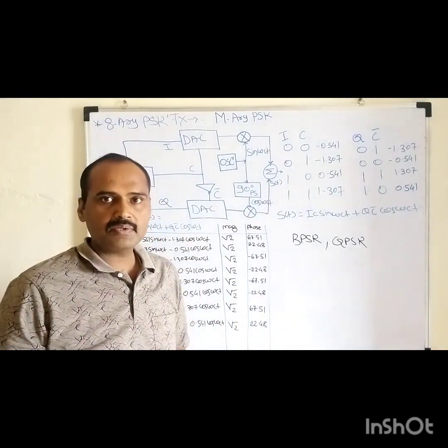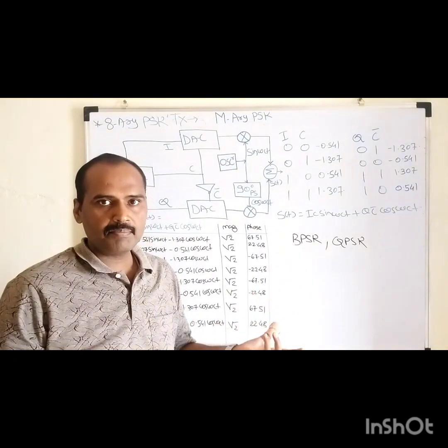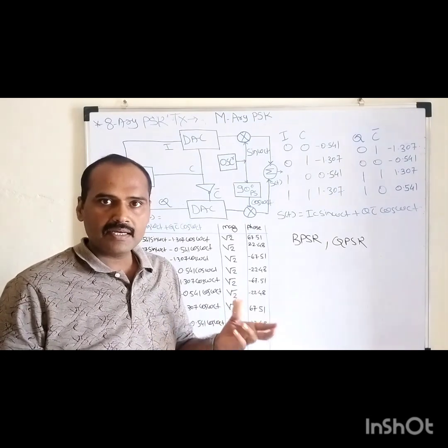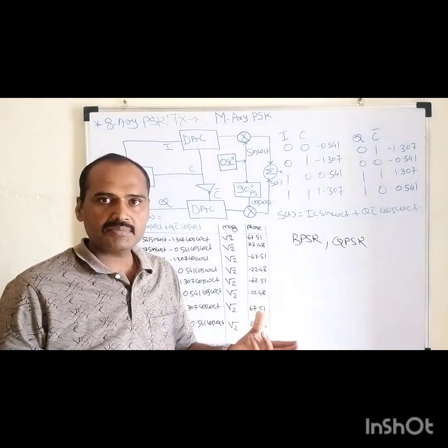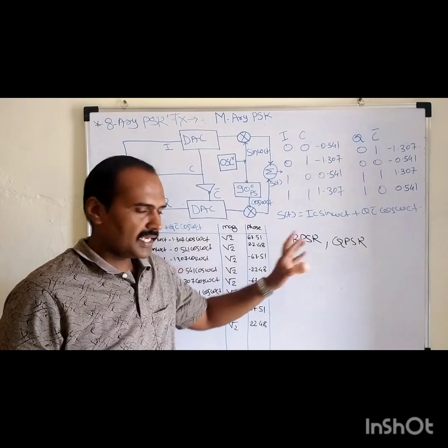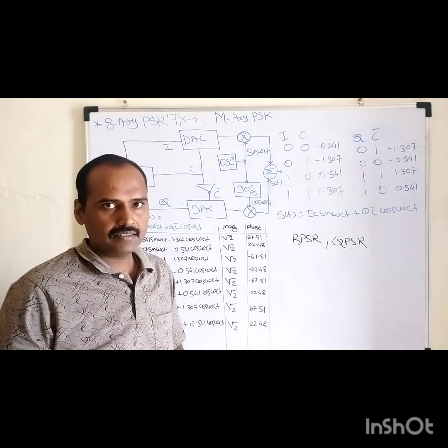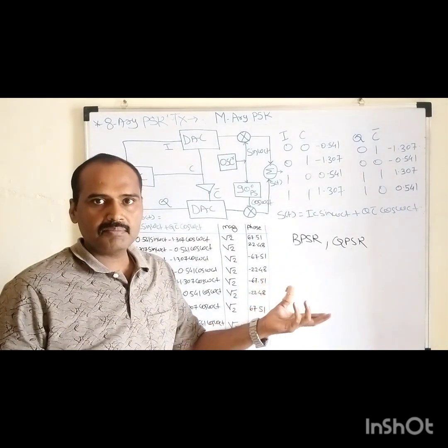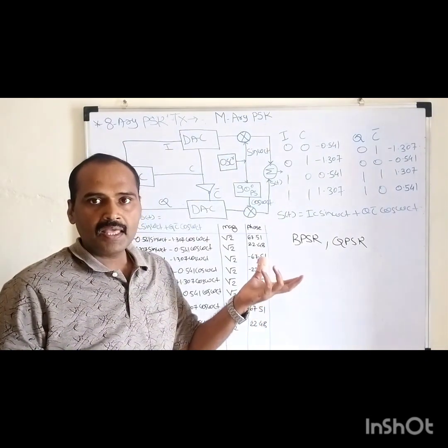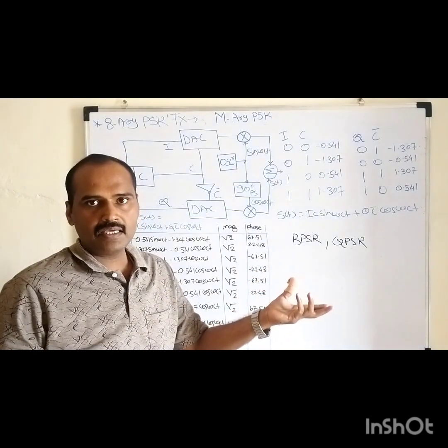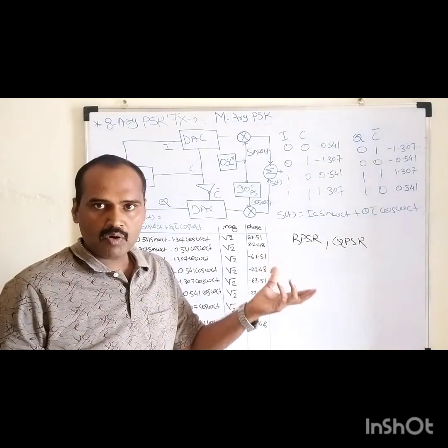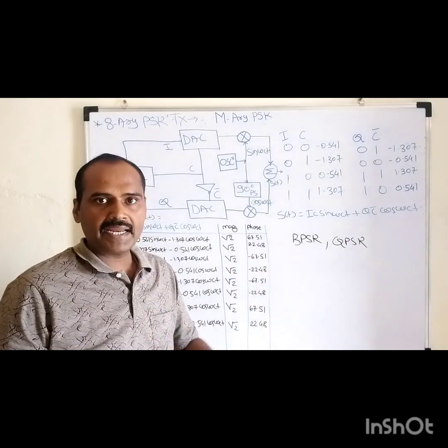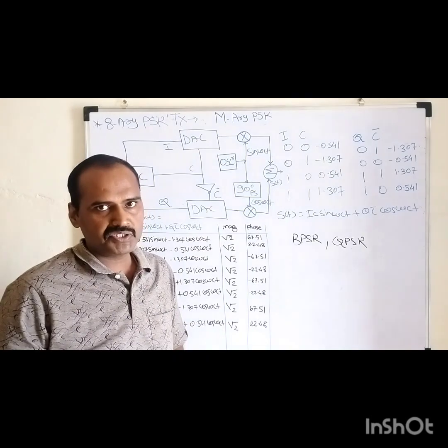First of all, we need to understand the objective behind this M-Ary PSK. Why go for M-Ary PSK over the conventional digital modulation schemes, the binary phase shift keying and the quadrature phase shift keying technique? In our previous two sessions, we discussed the basics of these two techniques. M-Ary phase shift keying uses M number of symbols for transmission, because it is an extension of BPSK and QPSK.